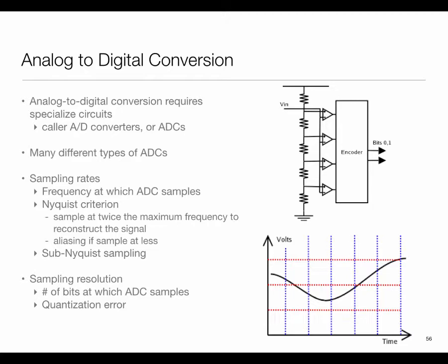So that's one part. The other one is adaptive sampling. If I know that the signal is not changing much, I can perhaps sample less often. And maybe I can even predict things. Let's take a concrete example. Let's say you are sampling an ECG waveform. We all know kind of what the ECG signal looks like, right? It's kind of a peak, and the peak goes below, and some flattish region, and again things.